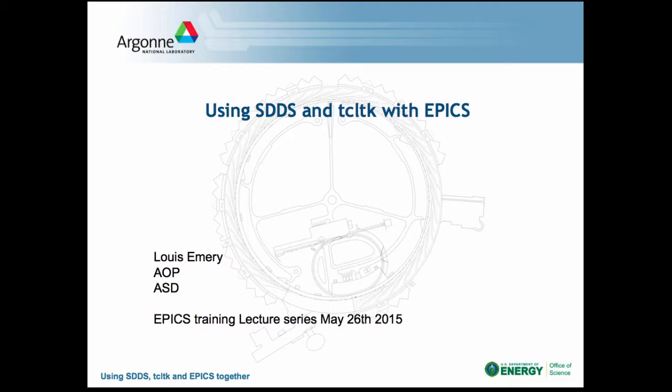We developed our way of doing things back in 1994 when we were commissioning the Linac and the PAR and then the booster and the storage ring. We started off running shell scripts and then realized, somebody from Jefferson Lab came and gave a lecture on tcltk, and we thought, well, this is the thing to do. It has a very clean syntax, and we can probably launch commands from that shell. So tcltk was a big thing in the middle 90s. Not so much now. People learn Python if they're new to the world of controlling things with EPICS.